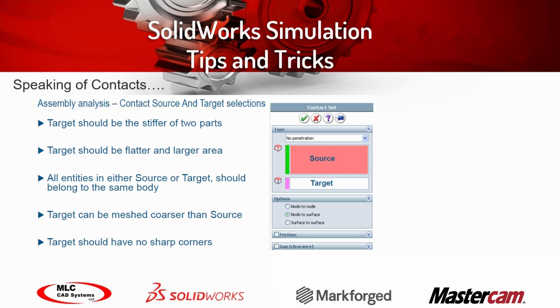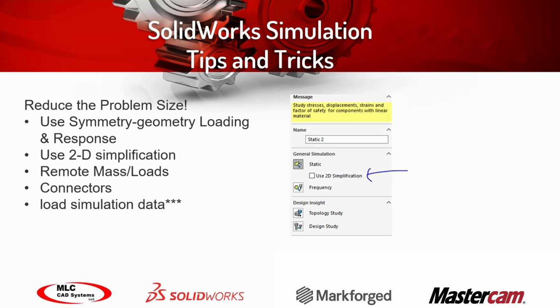Of course, as we saw through this, one of the goals here was to reduce the problem size. Of course, we get results in full 3D if we like, nice pretty plots, but take advantage of 2D simplification or even the symmetry fixture that I showed you. Again, that's under the advanced fixtures.